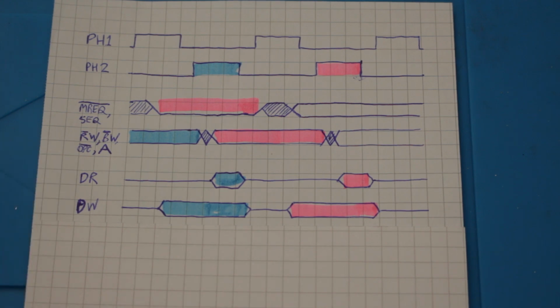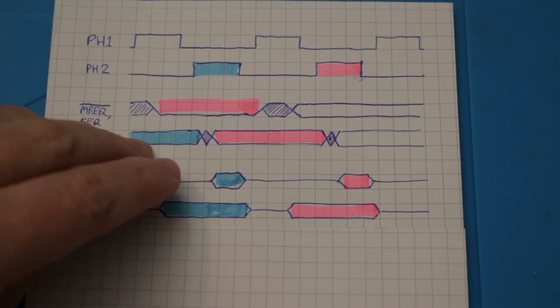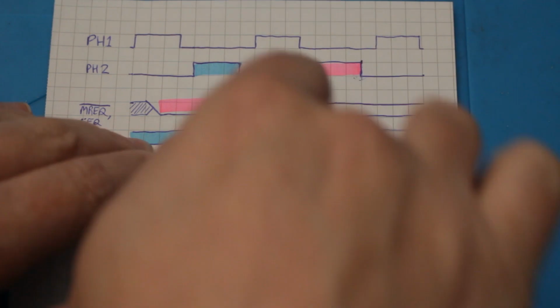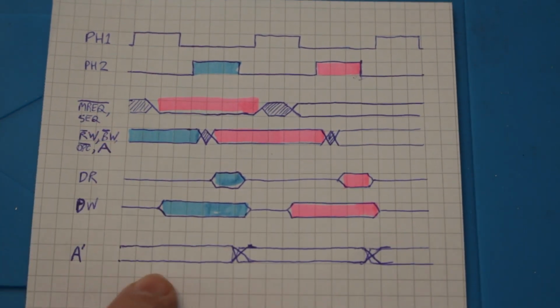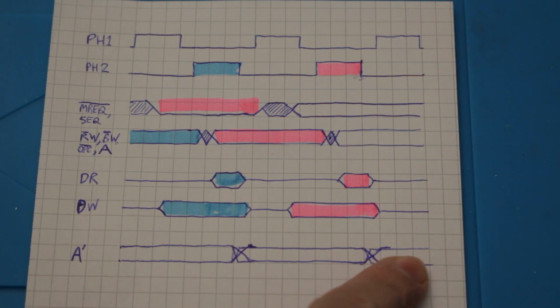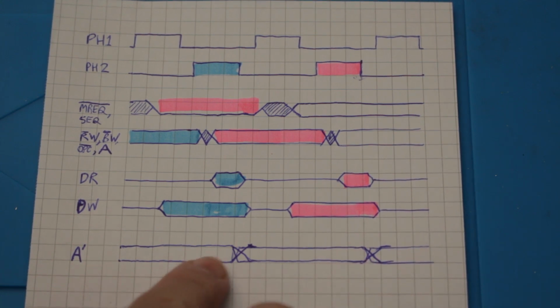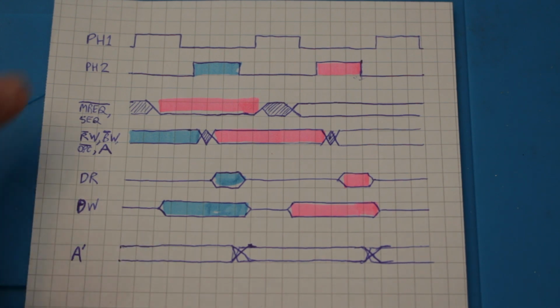One thing that helps us out a bit here is the address latch enable pin, which I did describe the meaning of in the last video. But this will show hopefully why that's important to have. So what I've drawn on the bottom here is a second version of the address bus, but I've delayed it. I've delayed all the transitions on this, and what I've done here is I've drawn this as if the address latch enable was being driven by phase 1, something like that. I think connecting phase 1 to address latch enable will essentially provide this behavior.